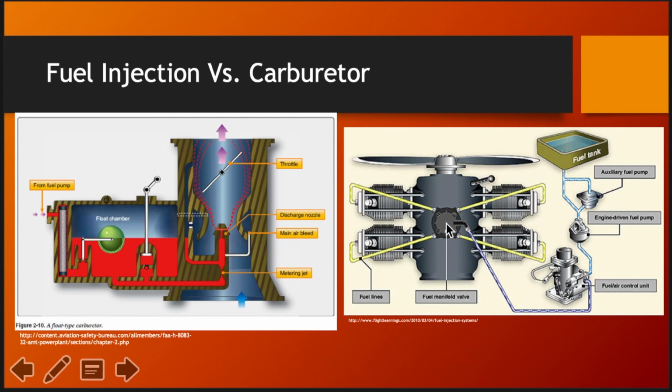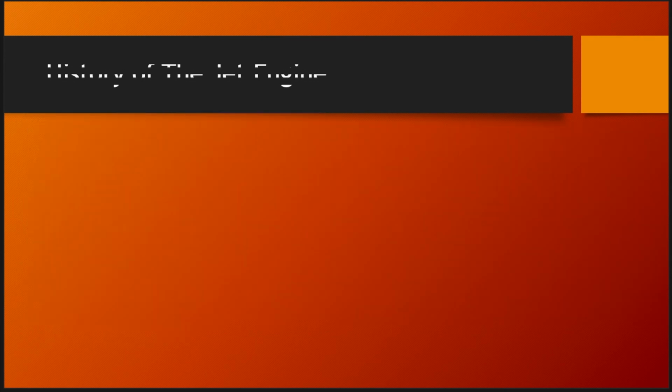The fuel injection over here, this is an older style of fuel injection, but it kind of helps you get the idea. So just think of your fuel tank, you have your pumps, and then it feeds through the throttle body here. And by the throttle opening and closing, it allows fuel to bypass through that, go up here to this, like a separator or a spider injection unit kind of a thing, and it allows fuel to flow through each of these fuel tubes into the cylinders. Newer engines will have separate fuel injectors per each cylinder.